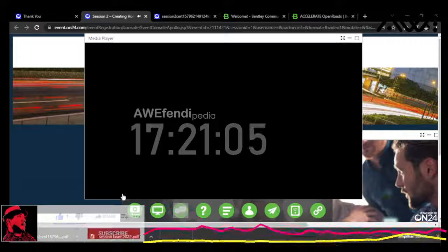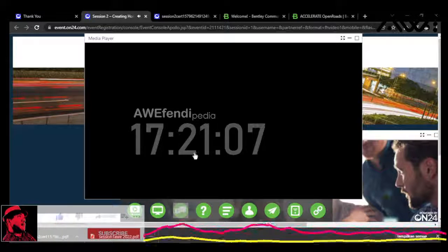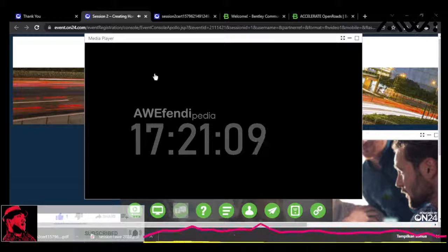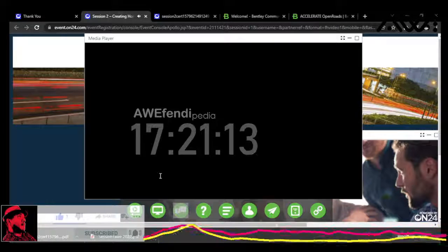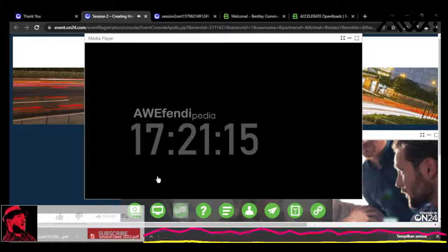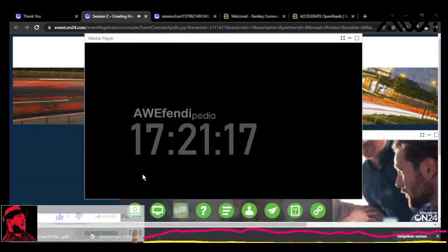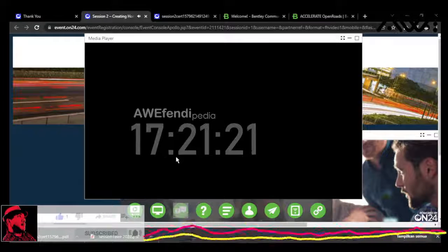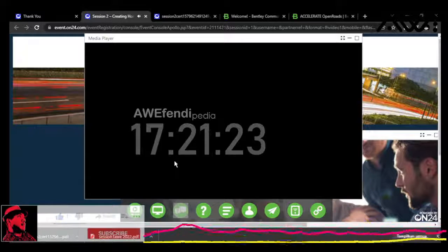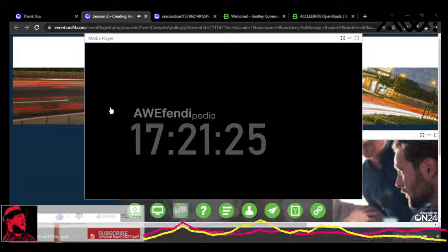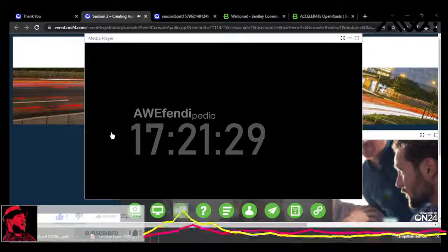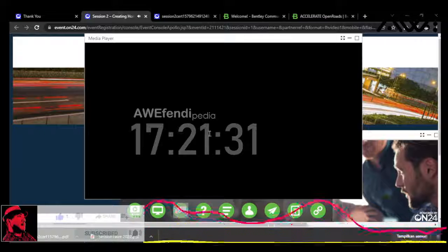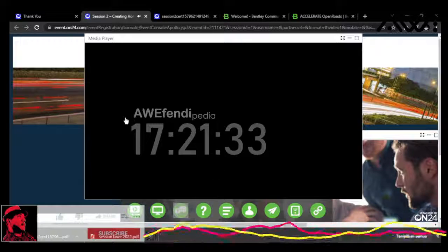All right? So I'm going to leave it on distance, and I'll just jump back over to this PDF. Since, again, this is what I'm adhering to, I'll see that first distance is 790.66. So I'll key that in. I'll click the Tab key or the Enter key. And this is the interaction part with that dialog, okay? To hold that value, I'll type it in and click the Tab key. Now that locks that value in place, meaning I have a fixed 790-foot segment.